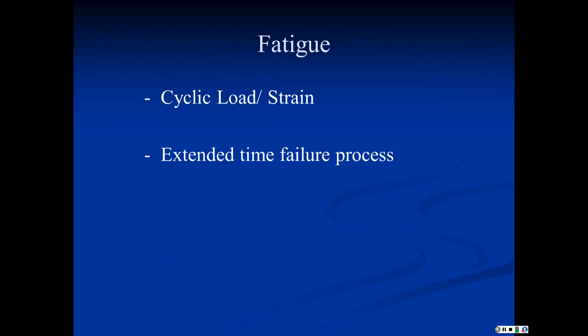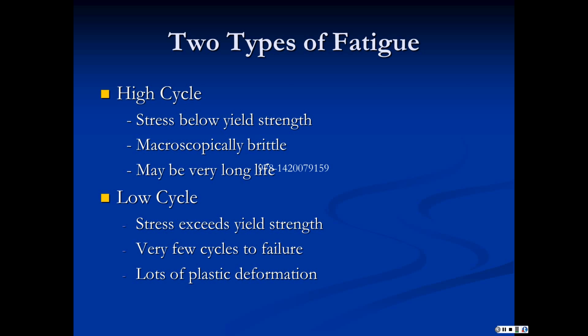It's simply a cyclic load or strain. That means we apply it, we remove it, apply it, remove it. Or you may have loads varying from one positive value to another. The key is it's a changing load, changing in time, usually at fairly regular, fairly high frequency, so that we're piling up lots and lots of cycles. And the result is usually a failure process that takes some time, often can take millions of cycles, years to happen, or to lead to failure. Although there are some cases where that time can be fairly short, obviously.